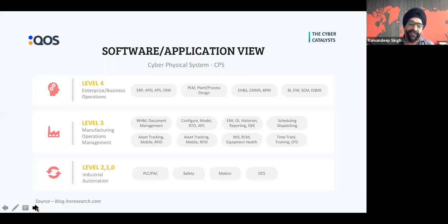So level 0 is absolutely the field device that's either electrical, mechanical, pneumatic, hydraulic, whatever it is, and then it gets controlled by some control logic, and that control logic will have some engineering information being sent to it. So that's sent by level 2 to level 1, and then level 1 operates the level 0 devices. Typically, these are on copper connections. That's most often what we see, using the physical wiring of RS-232 or 485. And also in the last 20-25 years, plants are basically seen with Ethernet communications.